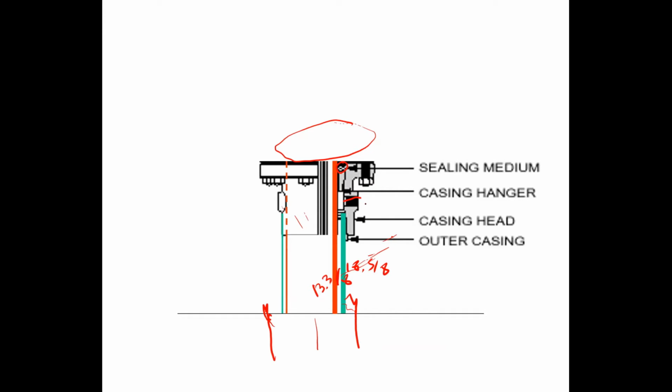It is a 2-inch double valve that production engineers find when they go to site. They measure pressure here and the fluid that comes out, because it can indicate problems with cement, corrosion, you know, and you can observe that.